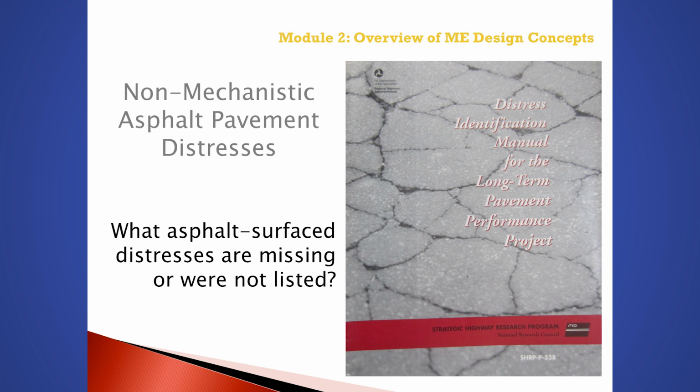As you start to use the PMED software for flexible pavement design, give some thoughts and consideration to those distresses and how they impact performance and IRI. Indirectly, some of the other distresses do impact the IRI growth or degradation in smoothness over time. So indirectly, they are considered by the PMED software in the design of flexible pavement. As an example, raveling. Raveling is not calculated within the PMED software, but does have an impact on IRI. So it is considered indirectly through the site factor variable.